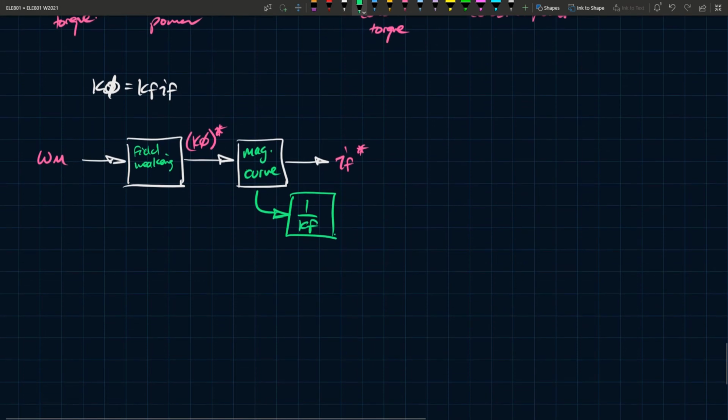Similarly, if we're going to talk about the field current, why don't we briefly touch on the armature current control, the set point for that. Yes, we control the armature voltage, but we do that through the armature current usually. So the VA and the EB and all that kind of stuff is usually controlled using IA. So it's IA and IF that are the control variables, not VA directly. The set point for the armature current we can determine by a torque command.